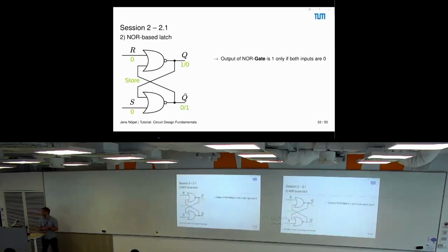All right, I would say we come to the solutions, and maybe we start first with an inverter. So what we want is first an inverter. Does anyone know how an inverter is built using CMOS technology? Have you heard of CMOS before? Yes, all right. So what is the simplest way to draw an inverter? It consists of two transistors. One is a PMOS transistor, the other one an NMOS transistor.